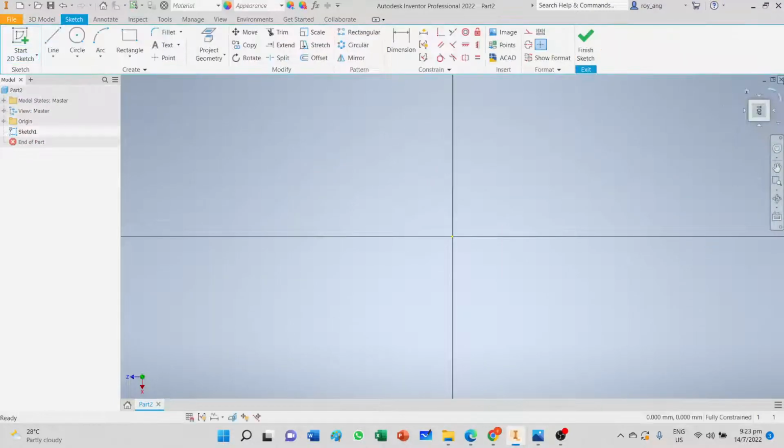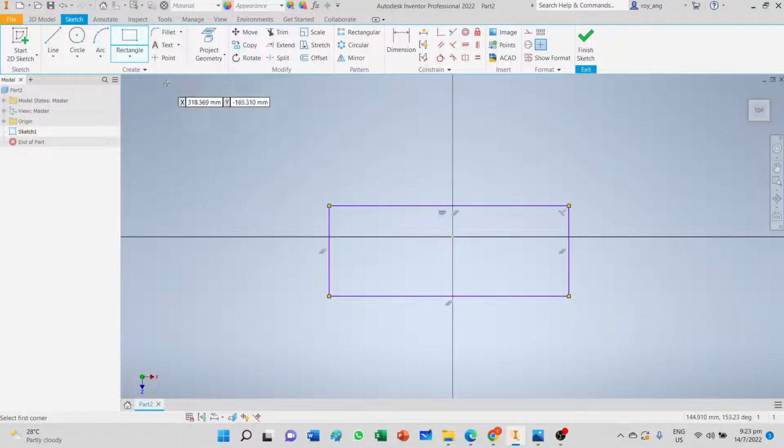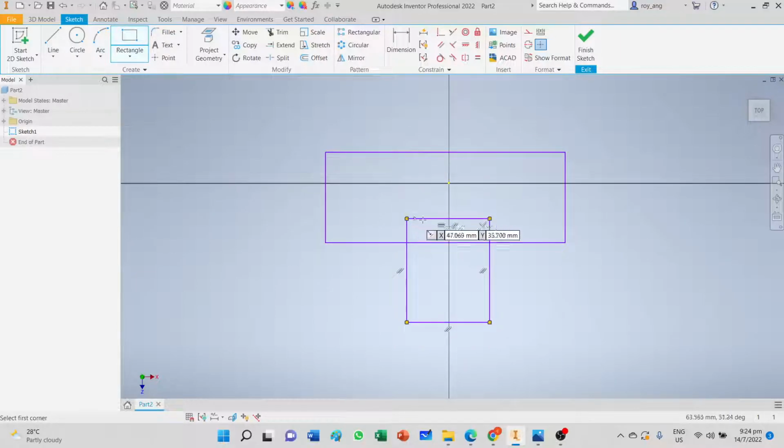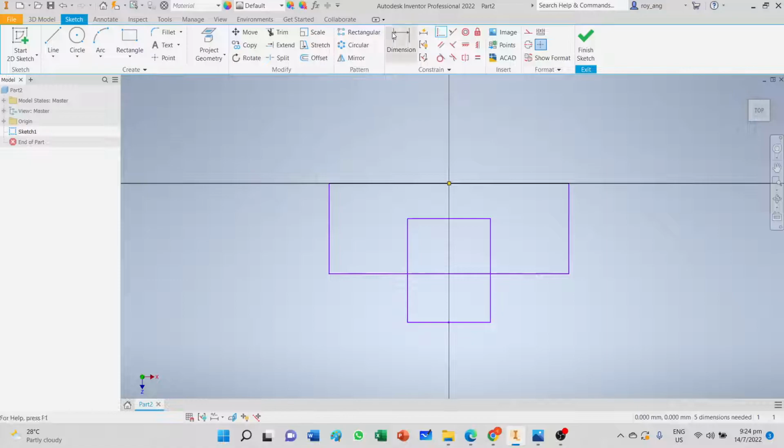And I'm going to draw it from the front view. And the way I do this, because it's T-shaped, I'll draw two rectangles. And I know that in the end, I will trim away these lines, so I won't want to make my alignments using these lines because then I will need to reconstrain them again. So vertically, I will constrain both rectangles to the center. And this rectangle, I'll constrain it to the center. Then I would make this coincide with this, so it will coincide.